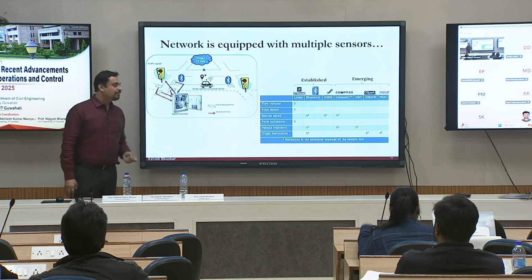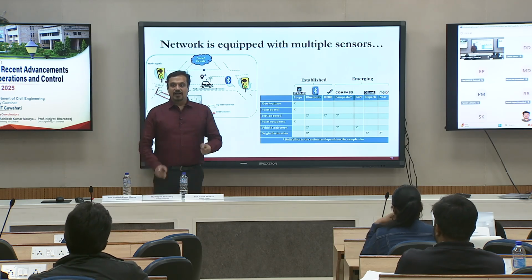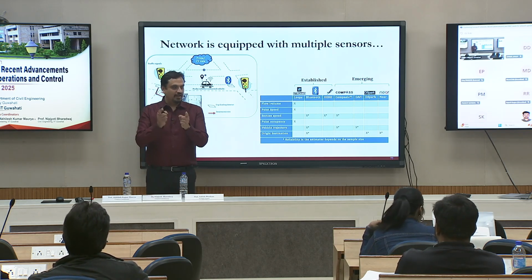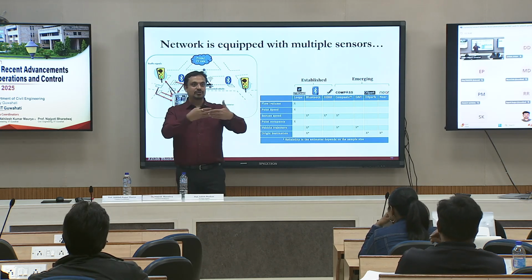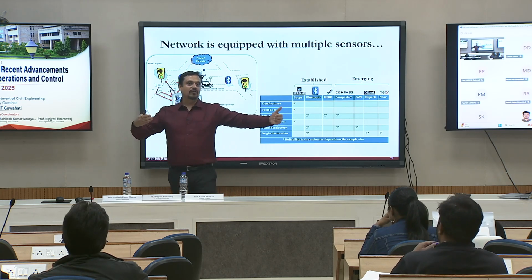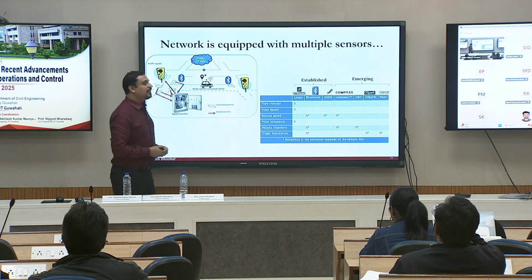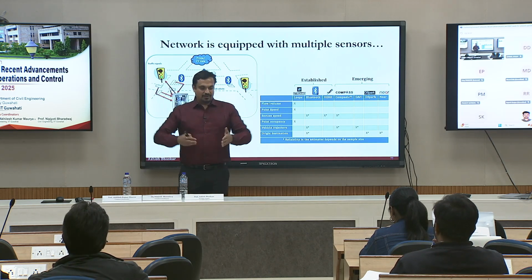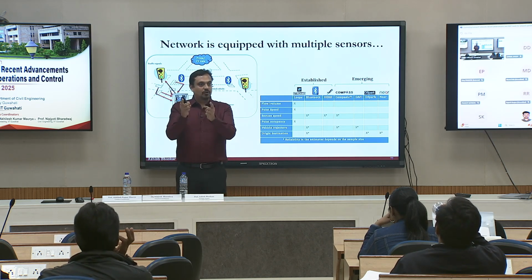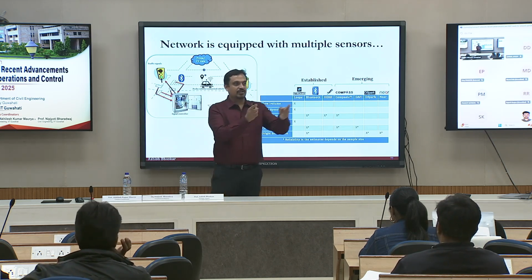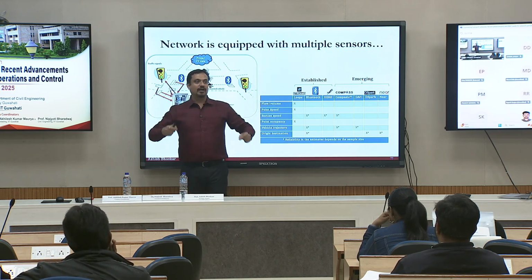In fact, here the data is quite huge, and they have their own sections defined, let's say 300 meter or 30 meter sections, and you have to stitch those sections together to have your travel time or speed profile defined for your study area. So when we use here data for our work, we have to do that work to stitch it together. They give you an average travel time with their own confidence for one section, then another section, and so on. Then you have to map the sections for your study corridor and get your values.